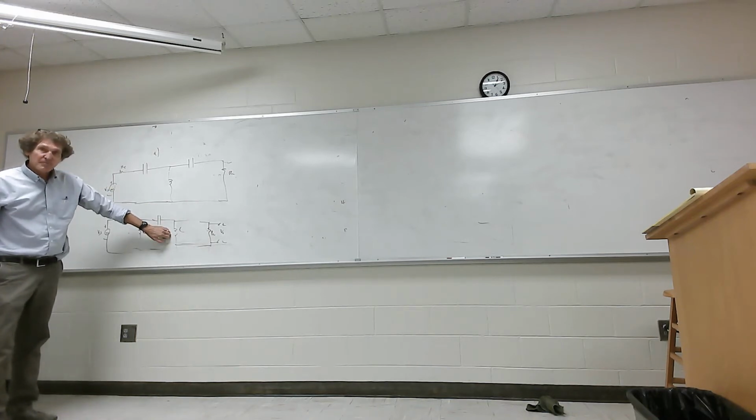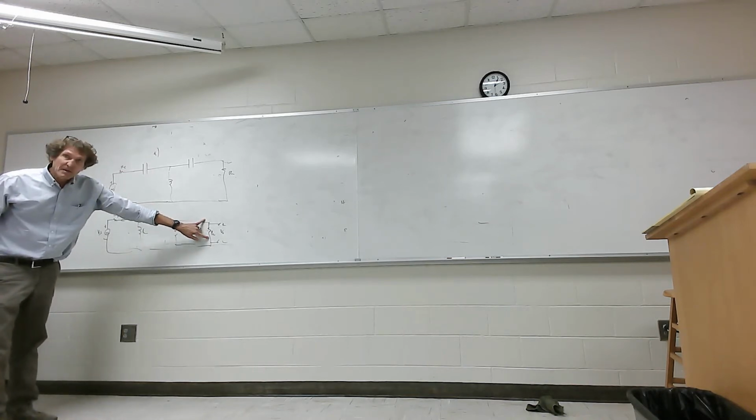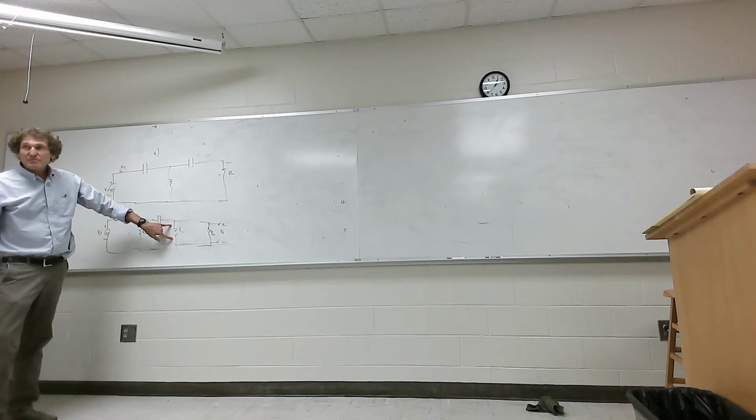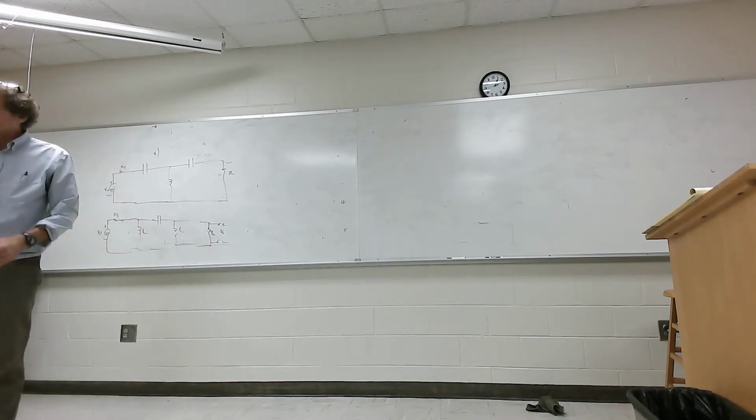It won't work. You can build filters this way, but if they're feeding a bipolar input, not a MOSFET or something like that, then you're going to have problems right there. And even MOSFETs have self-biasing stuff. So an inductor in parallel is not a wise thing to do if you're feeding any kind of transistor input to a chip that has transistors or anything like that.